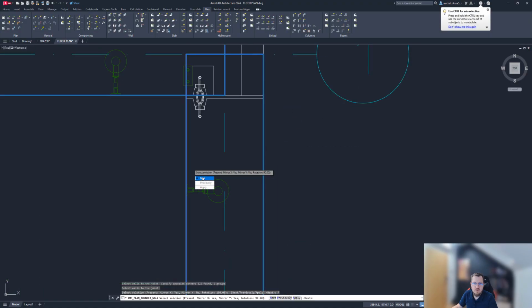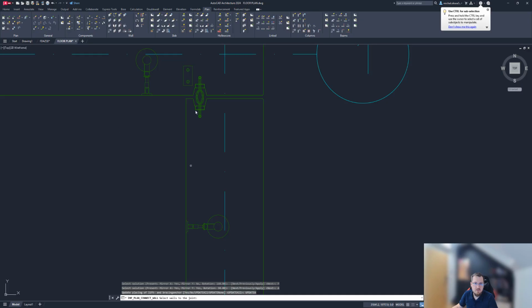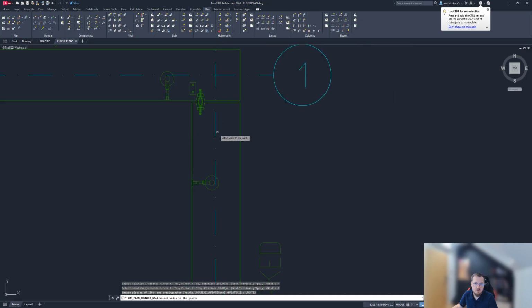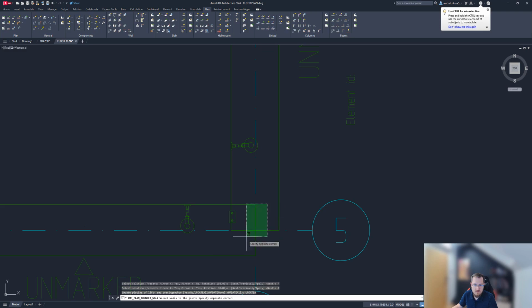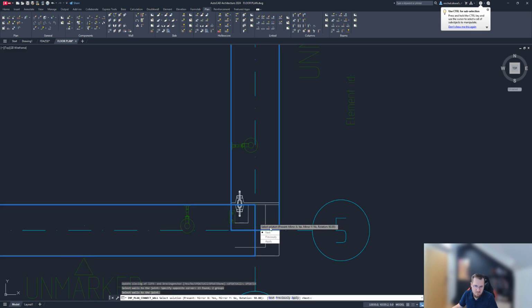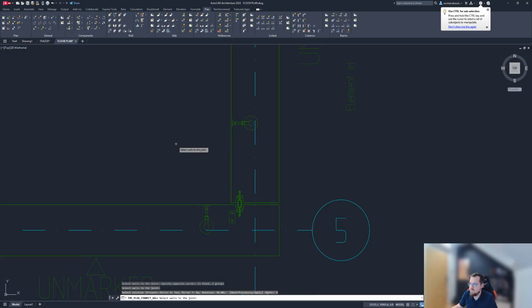You can change the orientation of which wall is the covering one, covering the other one. So I'm going to update that as well. As you can see, the walls are being aligned properly like that, and I think that's the one that we used on the top. Should be similar. And as long as I'm in this window, I can go ahead and add those casting material.